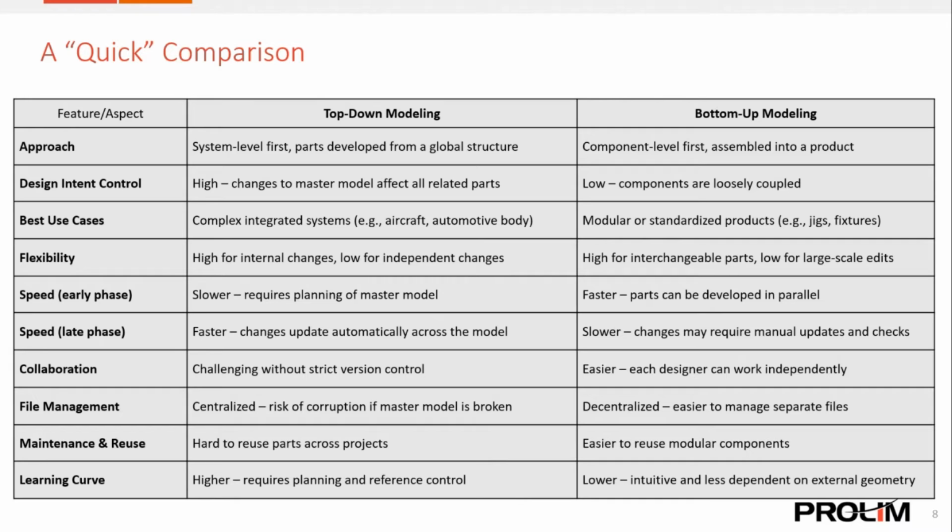Well, let's say a certain hole or a cutout or a bore for a bearing is a little too big. Now I have to go into that component model and change that, or do whatever I need to do. But if I already have a driving relationship off of the bearing, then I don't have to do much other than maybe replace the bearing part, and it'll automatically adjust that bore as well.